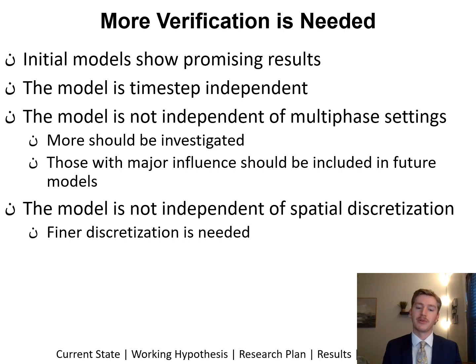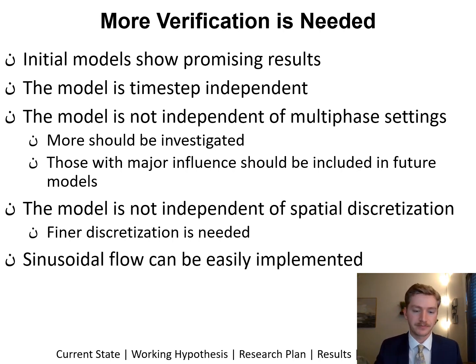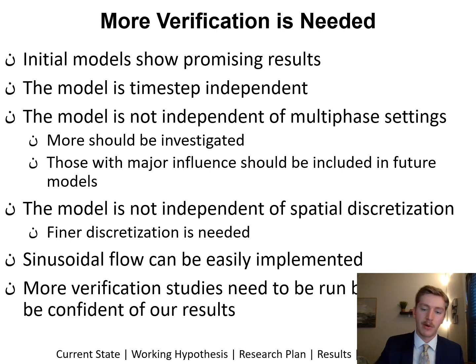We also found that the model is not independent of spatial discretization yet, and further discretization studies need to be conducted with an even finer mesh. We did find that sinusoidal flow can be easily implemented and will need to be implemented with the other settings and finer discretizations for a final CFD model. However, more verification studies need to be conducted in order to be confident of our results of the final CFD model.